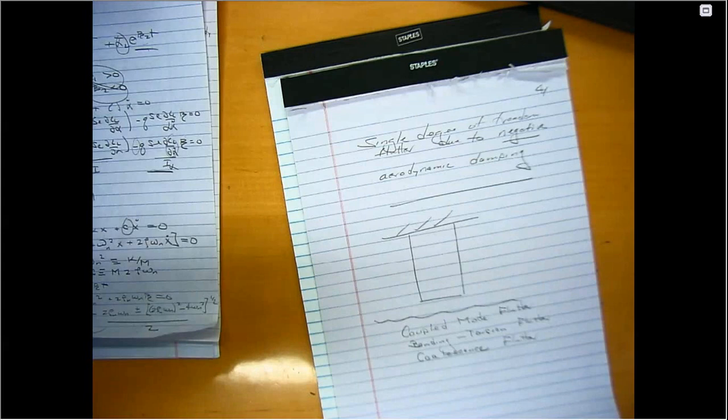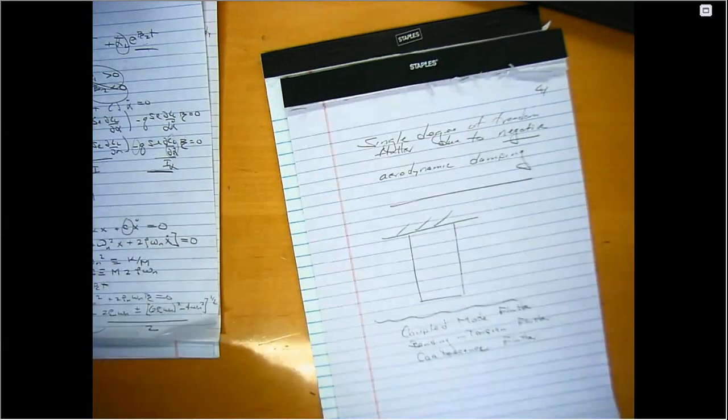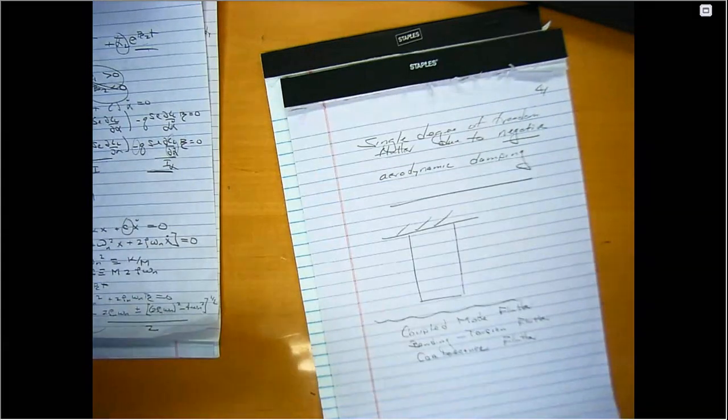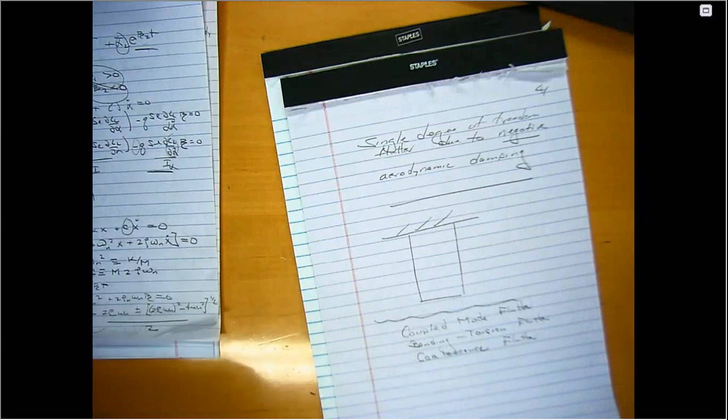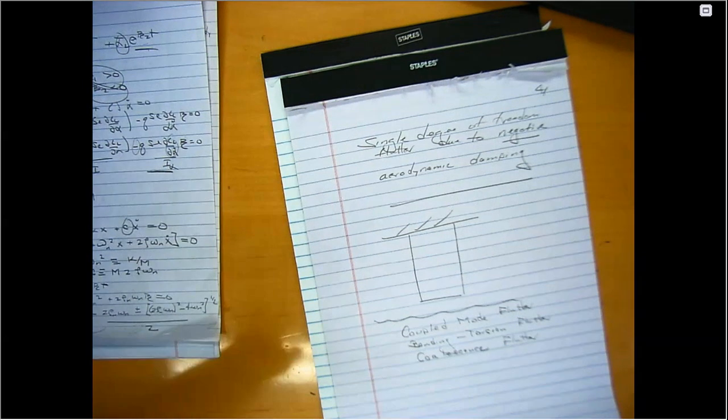And near the Q value where those two frequencies come together, that's usually a flutter condition. Not universally, but often. And so it's very characteristic if you trace the frequencies of modes in a wind tunnel, as I'm increasing the wind tunnel flow velocity, the dynamic pressure, you'll see those two frequencies tending to come together. And when I see them coming together, I know I'm probably approaching a flutter.